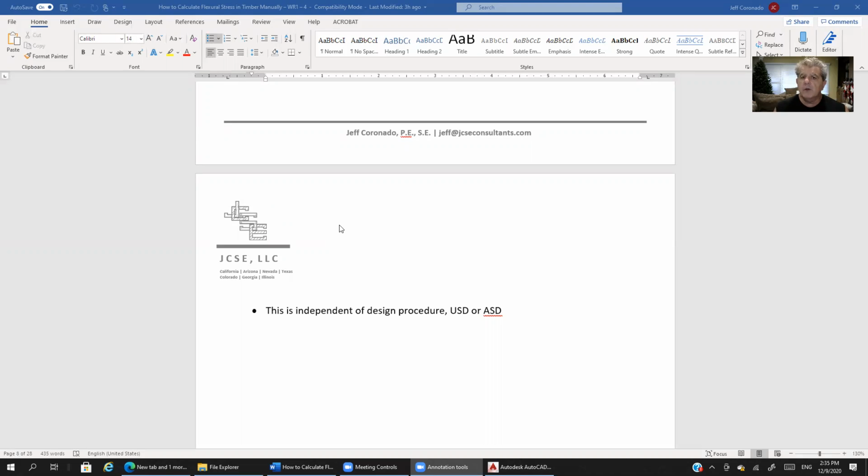So even though I know that in school, what is stressed upon you is ultimate strength, that's true for steel. Steel is kind of iffy. Steel kind of goes both ways. Concrete, clearly, it's been ultimate strength for a while, but timber's standard of practice is probably still to work in allowable stress design.